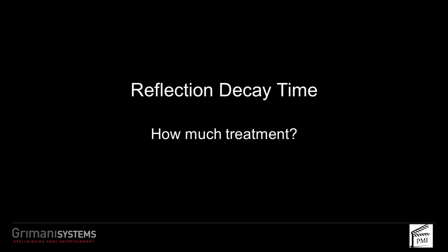So here's the if and or but. If a room has a lot of standing waves, which means that the energy is bouncing around the room and resonating, I talked about this last week, and you put good bass absorbers in the room that get rid of the resonance, well, that resonance is now not pressuring the walls. And so you've reduced the amount of standing wave energy, which means that the walls are less excited, which means there's a little less energy going to the neighboring rooms.